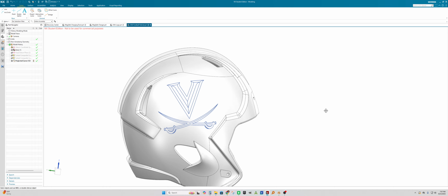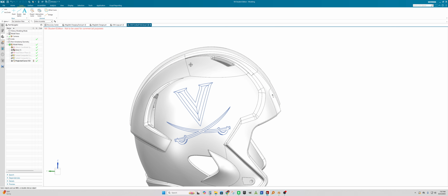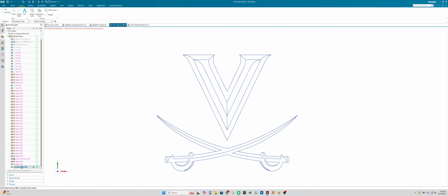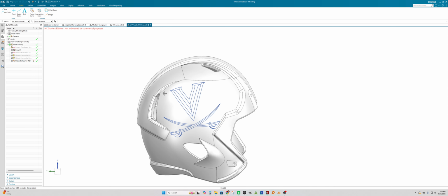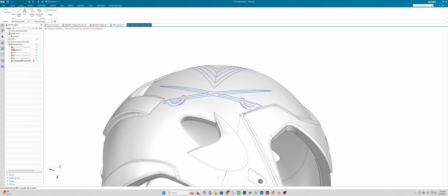And I think I've got the logo a little smaller than I want, which is, it's better if the logo is bigger. It'll print easier, show up better. In order to do that, I could go to this file that I created before and go to my scale curve and change that. You know, let's go up from 1.1 to like 1.25. It's a scale factor, and then that increased it, and so it updated everything else that I did since then. It just follows the tree, just updates everything in that tree.